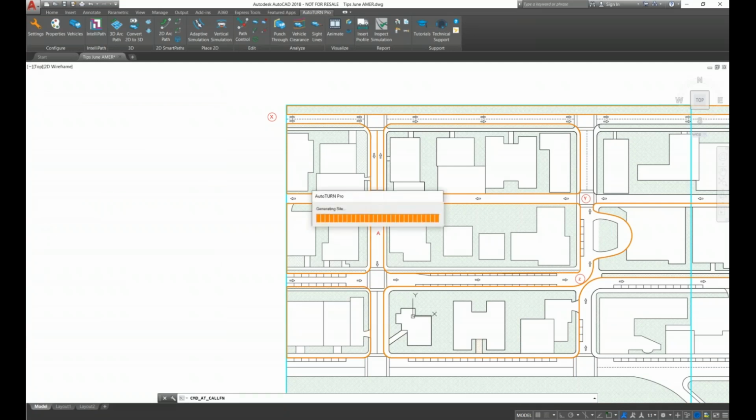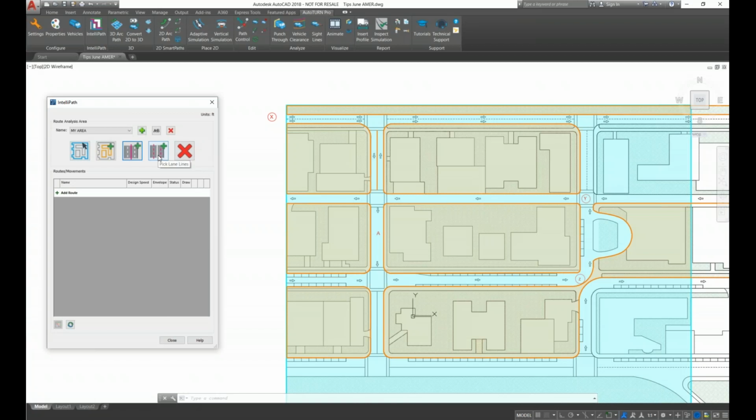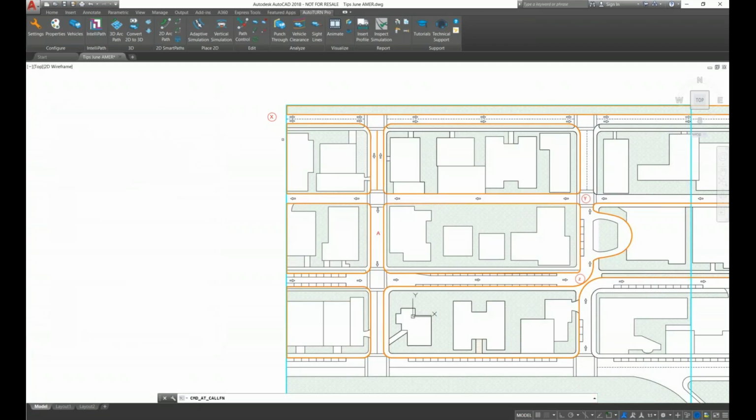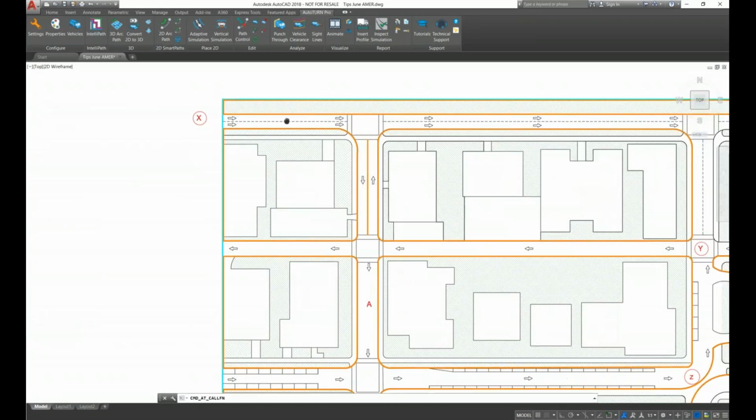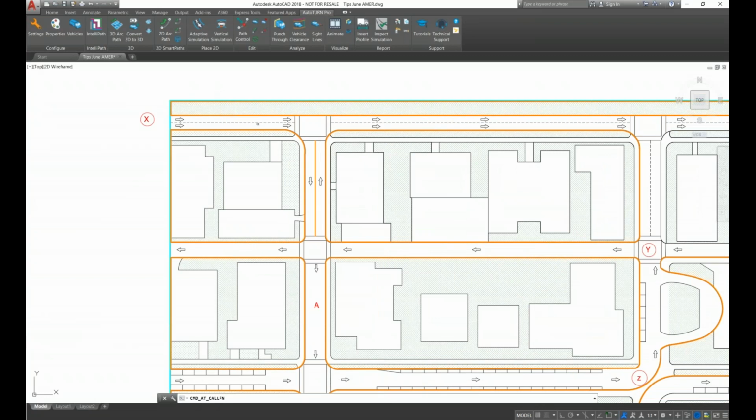And right click, and this tool is for lane lines. In this typical situation, this is a one-way road with two lanes. So if we select these as the lane lines, the software automatically detects and recognizes that a vehicle has to be oriented along these lane lines always.